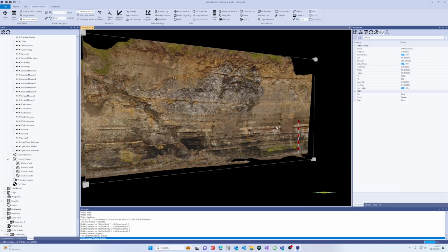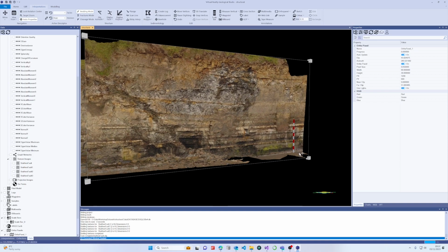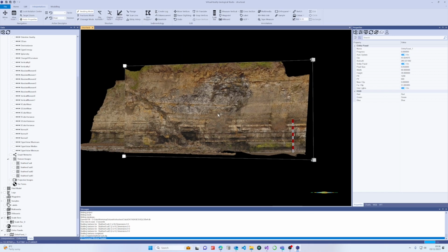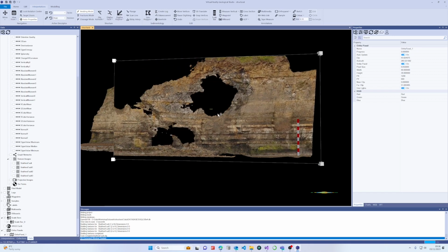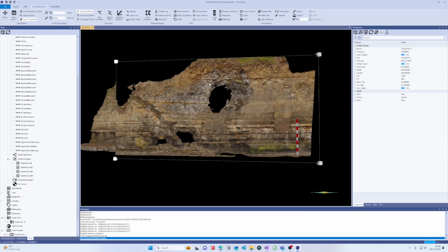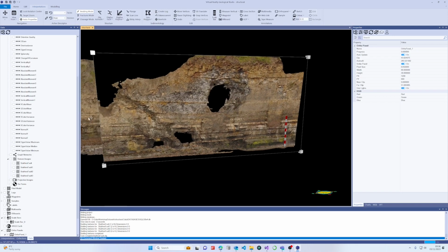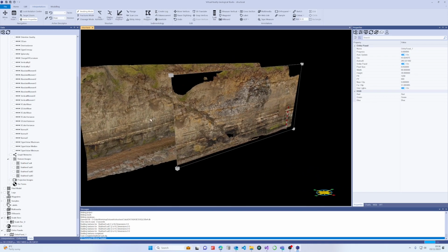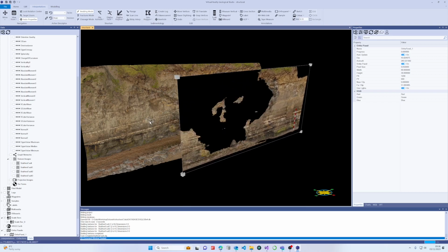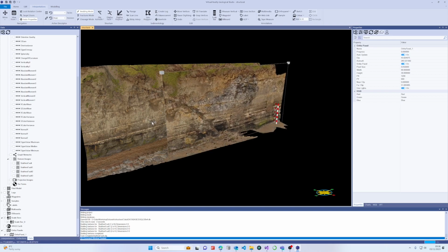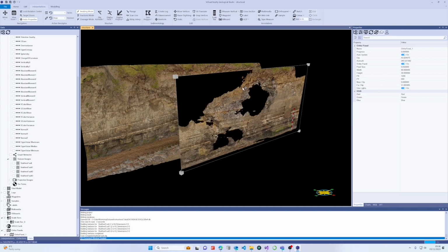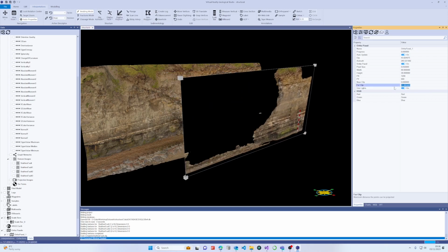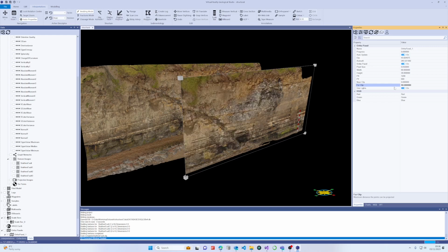Also note that the scale bar gets projected onto the ortho panel as well, so that's good if you want to incorporate a scale. As I move further away, you start to lose parts of the projection. That's because the projection only will work for a certain distance. So if you go too far away, it no longer projects. You can change that by modifying the near clip and far clip planes. Just going to put that up to 80, and it should project everything again.